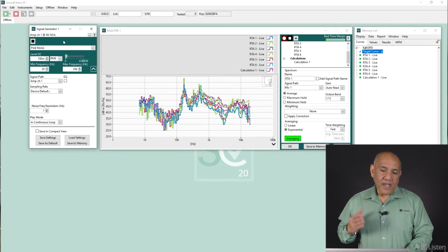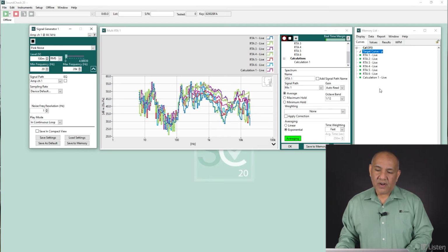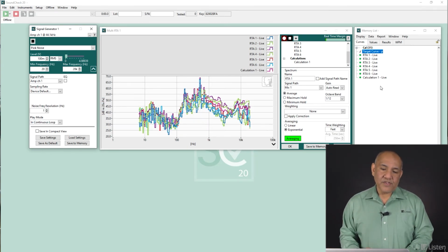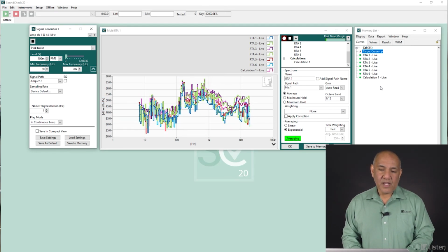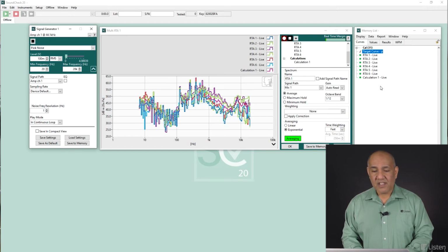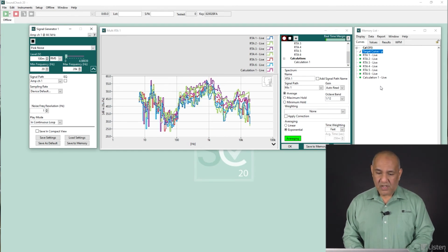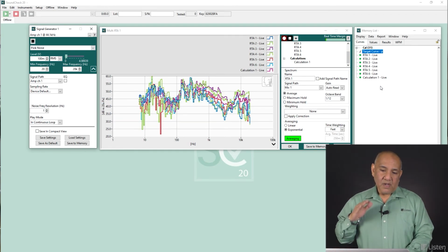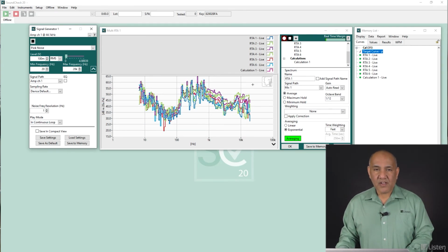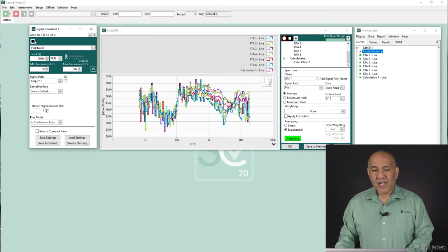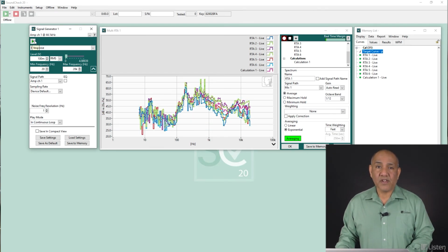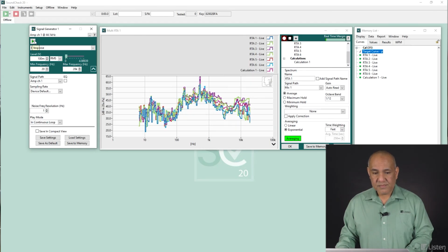Now, if I had a golden reference target in my memory list, I could drag that into the graph on the left side, and an engineer can tune the DSP inside of the vehicle to best meet that target curve. Okay, so again, this is a 6 mic array using a power average calculation. Typical application is tuning an automotive in-vehicle from the head position.